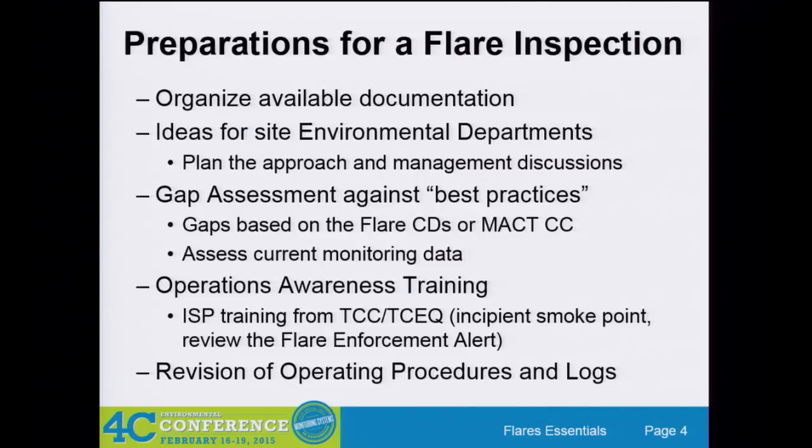Another thing is operations training, getting your guys away from just jamming the steam on. Because really, they turn the steam on, when did they turn the steam off? That's why the EPA wants these automated systems put in, because you find too many times that there was an emergency, smoking flare, steam went all the way up. They're dealing with the emergency. Emergency's over. What triggered the operator to go back and turn the steam down? Was it 10 minutes, an hour, a day, a month? Did it ever get turned back down after the last upset? That's where the EPA's concerns are.